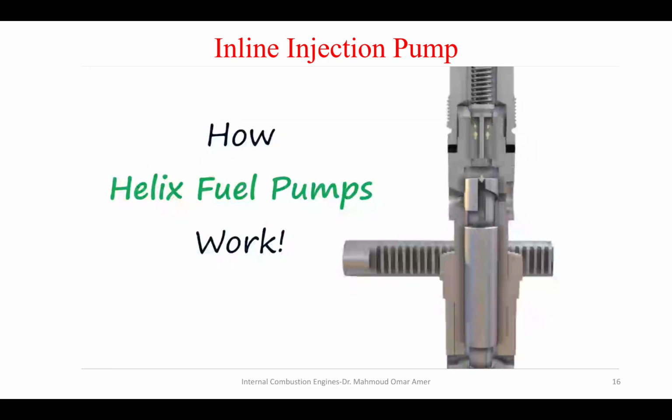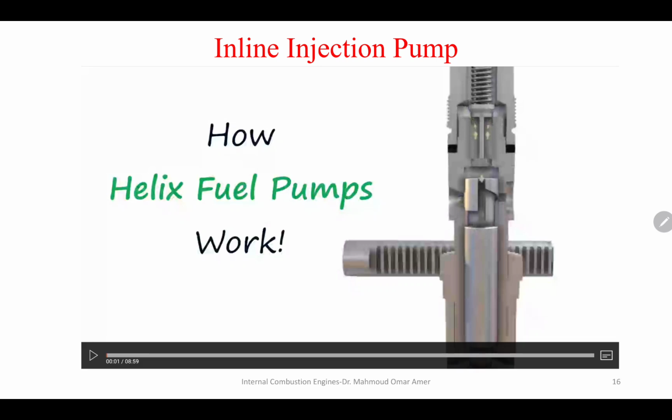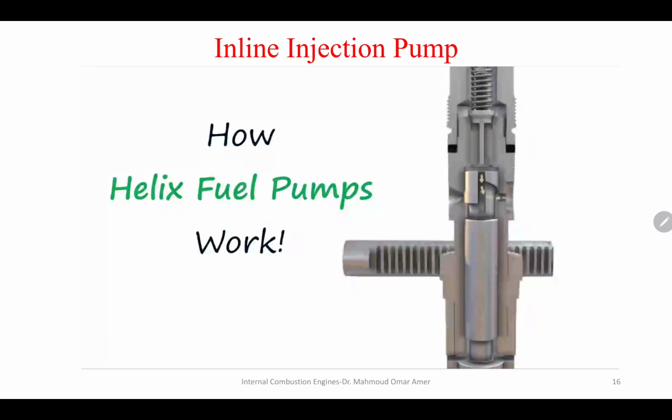Any slight upward movement, like this, will open a small passage from up here to the return port. So now, any continued upward motion will push the fuel back through the return port.